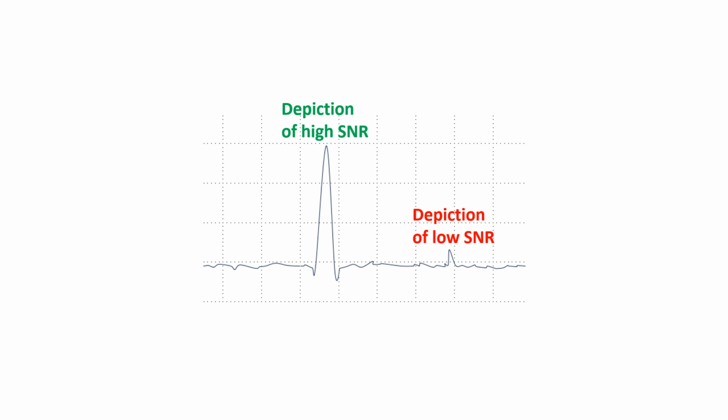Noise level can be reduced and signal strength improved by adding low noise amplifiers (LNA) at the antenna output before the receiver input. These two techniques are used in satellite communications where the signals are expected to be of low level.